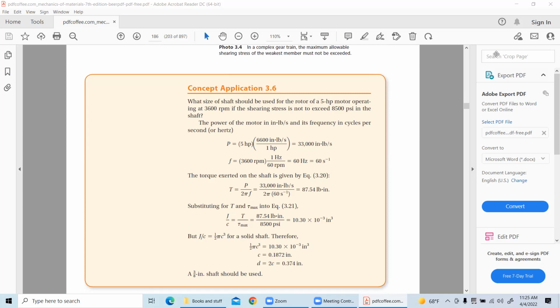Look, the whole twisting thing is about applied torque. The shear stress is about reaction torque, because stress is more like a reaction thing. I am putting a torque like this. How the shaft is behaving in terms of shear stress depends on the reaction torque. But the twisting is applied torque. So in an exam setting, you look from one side, make a decision, keep on making cuts, but keep on looking at the applied torque.